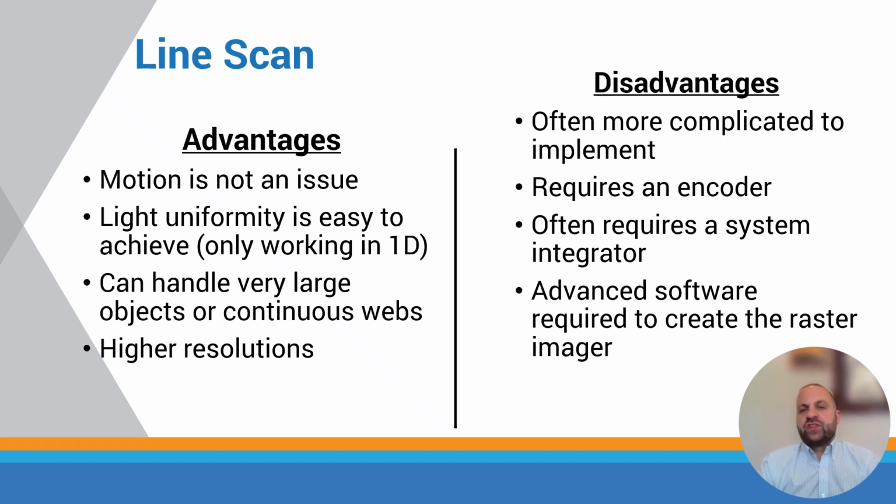Now the disadvantage is it can be more complicated to implement, and we know there's a lot fewer people turning to line scan because it is more difficult. It often requires a system integrator, it does require an encoder, and you need advanced software to create the raster image.